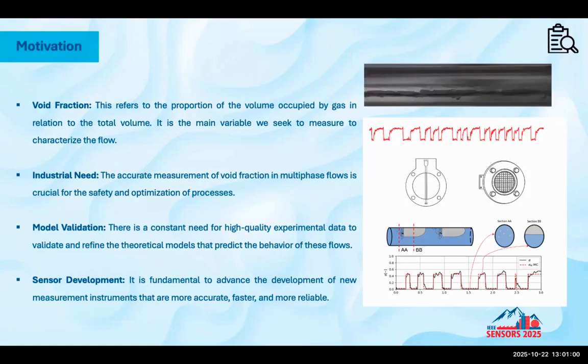Here we have a video example of a flow. This is slug flow, where you have a large gas bubble and the liquid mass phase. And here we have an example of this void fraction measurement, where the peaks represent the passage of a gas bubble, where the void fraction is high, and the valleys represent the passage of a liquid mass, where the void fraction is low.